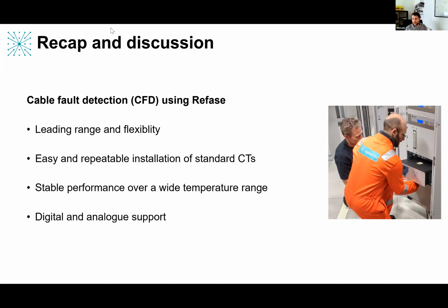But yeah, there's potentially things we can look for when you've got high frequency monitoring of the signal, and that's something we're looking at exploring going forward. I guess as soon as you introduce voltage, you have the complexity of getting an earth or getting a reference there, and then you've got the insulation challenges and the cost rack up for that, whereas current can be retrofitted very quickly. Yeah.